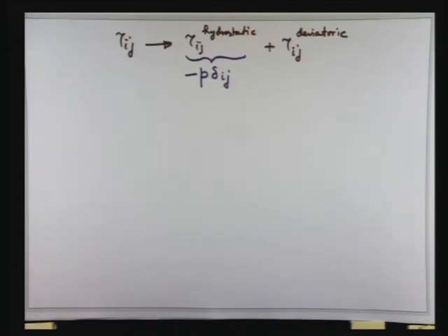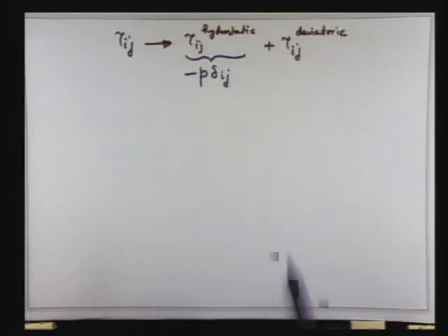What kinds of deformation does the fluid have in general? See, the fluid has volumetric translation, but the translation culminates in the form of volumetric deformation and angular deformation. Angular deformation is shear deformation, plus the fluid has rotation. Now the deviatoric stress, which is related to deformation of the fluid, out of these three, there will be one particular component which will not give rise to any stress. One is volumetric deformation, another is shear deformation, another is rotation. Out of these three, one will not give rise to any stress.